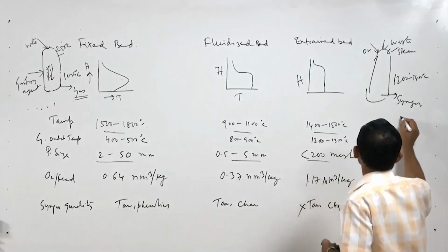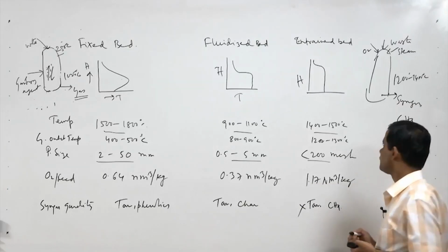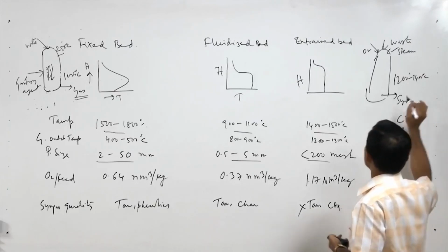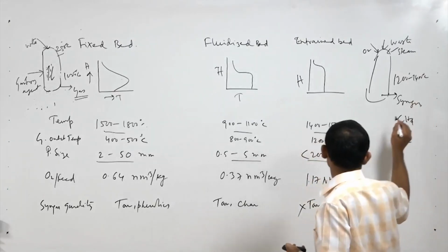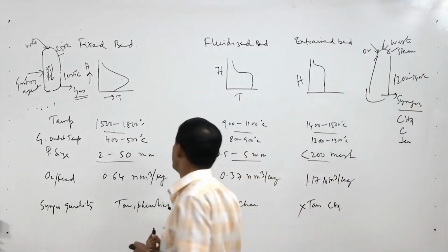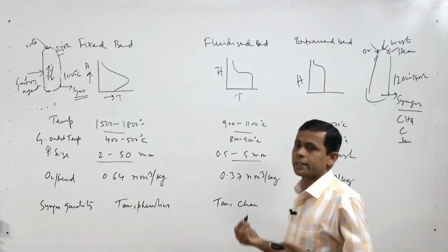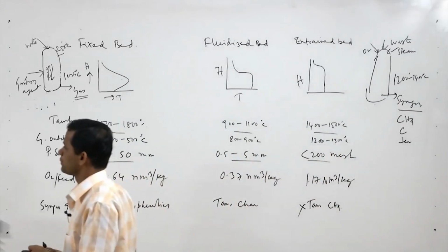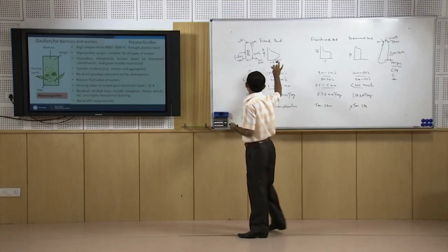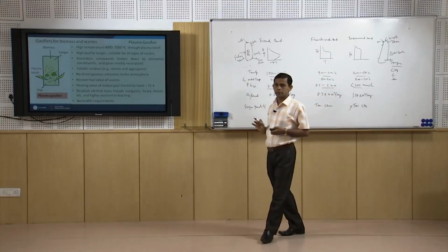This syngas contains less CH4, no carbon, no char, and no tar. This is a superior quality of syngas, and it is mostly suitable for chemical production, and is also suitable for very large scale production. These are three conventional gasifiers which were developed on the concept of coal gasification.